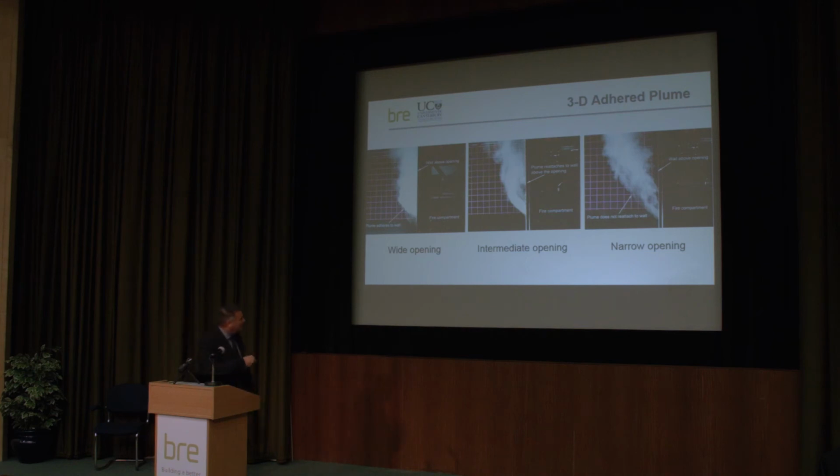So we've got a wide opening here, 10 meters. Here's our fire compartment, side-on shot. Out comes the plume. Here's a wall above that spill edge, sticking to that wall, entrainment into one side. That's typically what we would expect.